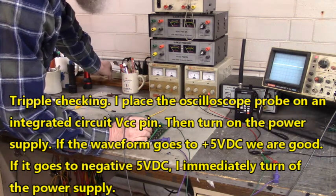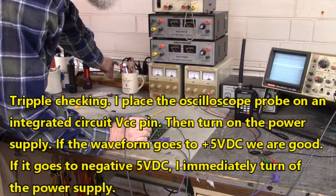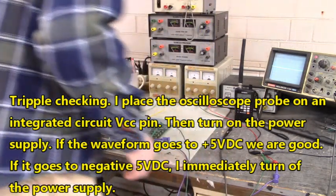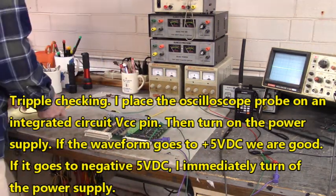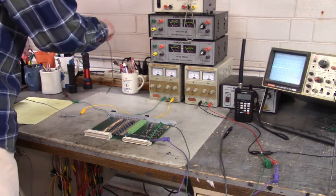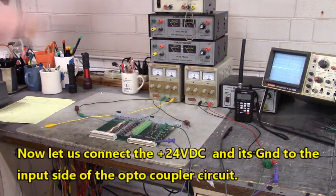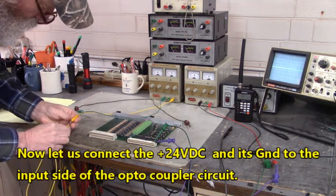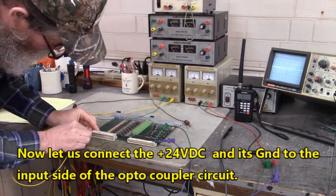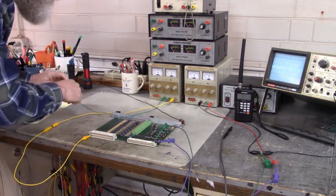Now when I apply power to that circuit, I place the oscilloscope probe on VCC of the logic ICs and turn on that power supply. And if things are good, it should go to plus 5 volt DC on the oscilloscope and not negative 5 volt DC. Here's the 24 volts that we're applying to the input side.